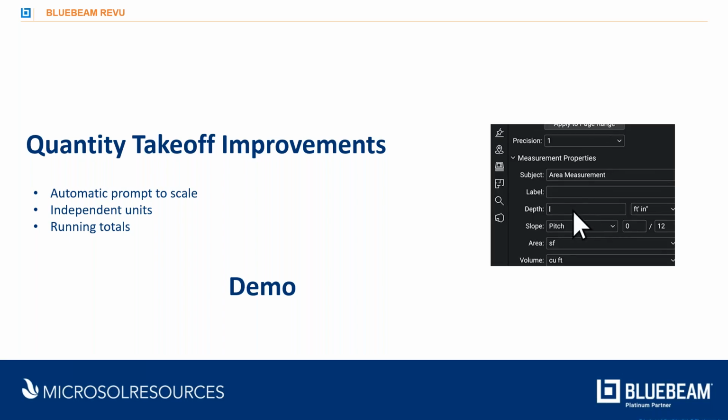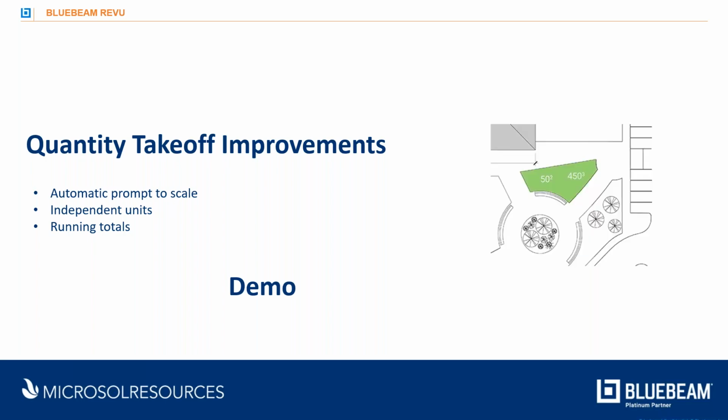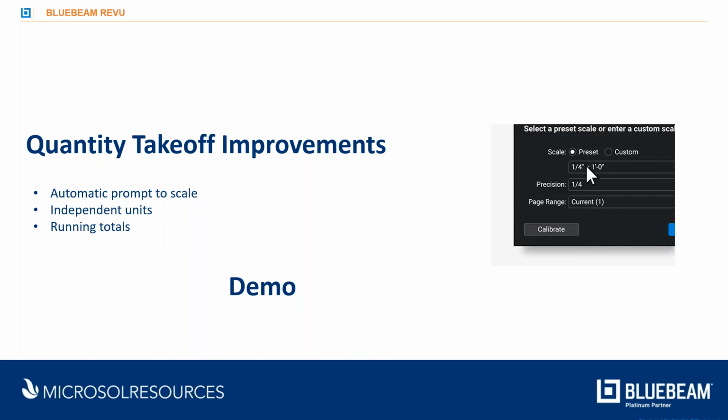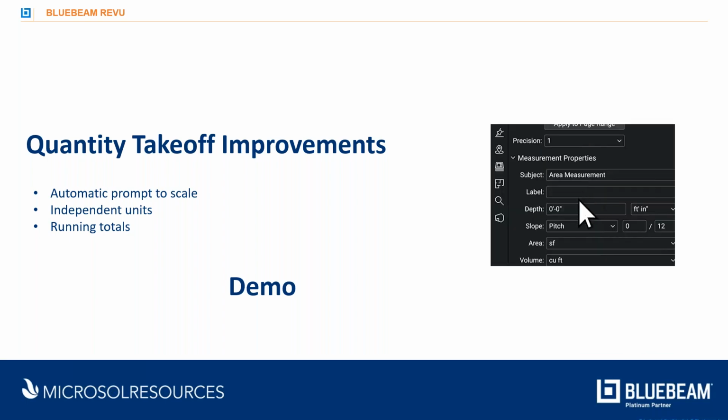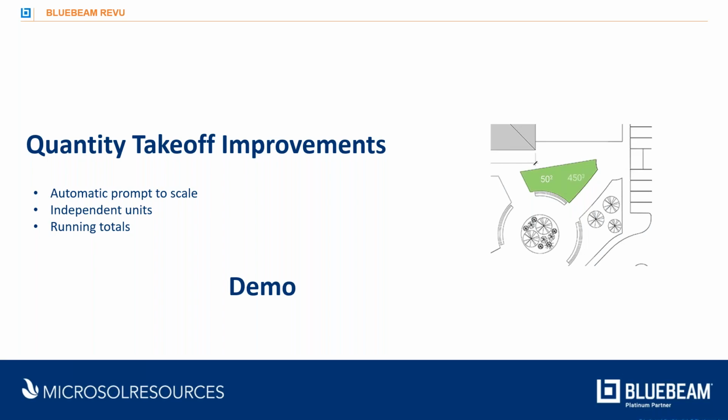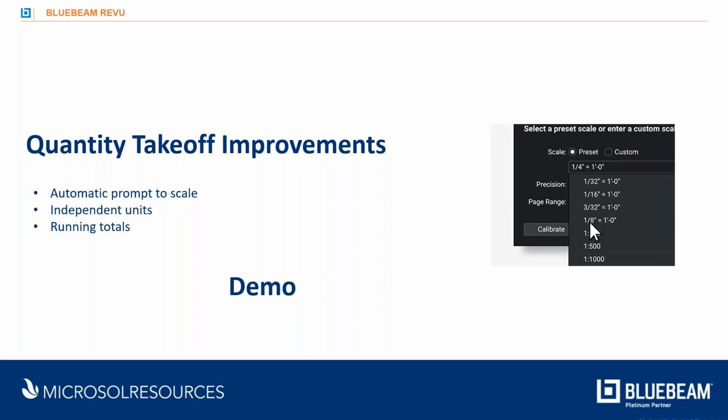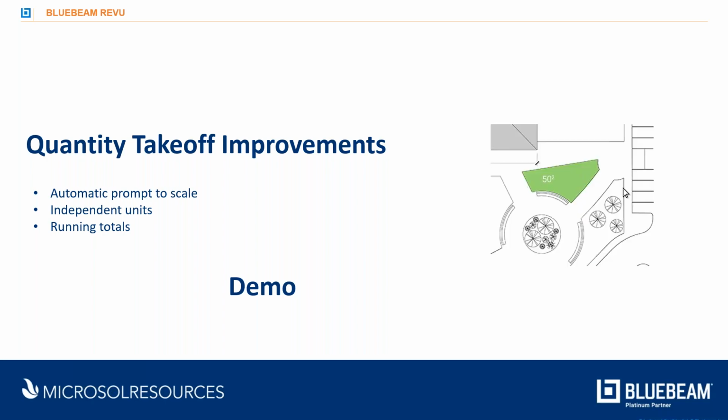Imagine you are putting in areas, and in previous releases, that particular markup tool could have been square feet or could have been square yards, but can't be both. Well, so you had to go through all kinds of gymnastics in the markup list to get square yards to square feet or vice versa and figure out how to assign costs, and it was ugly. Now we can independently assign these values, store them in that markup so that when we use carpeting, for instance, we'll get square yards. If we do tile, we'll get square feet. I'm going to show you how to do that.